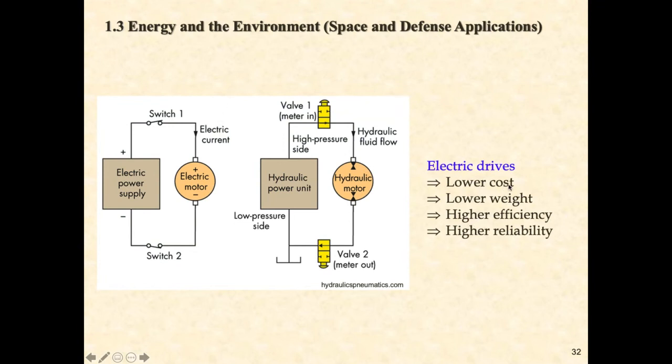The cost can be lower, the weight can be lower, and efficiency and reliability can be higher. It is because this system can be relatively simple, right? For example, we can use a switch to replace the valve, and even the electric motor itself should be much lighter than the hydraulic motor. So that's why now we prefer using electric-driven systems.